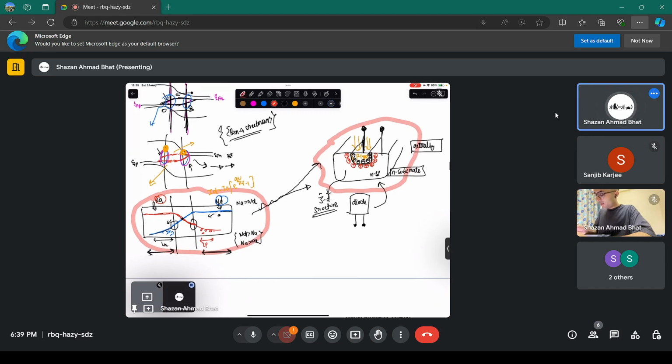Now you see that you have the depletion region throughout this particular structure. So you have to solve the electrostatics accordingly, but we don't care about solving the electrostatics in 3D, because the 2D and 1D cases are enough for us to visualize how the carrier concentrations are changing inside the diode. But this is the actual representation of how the diode is made in real life.